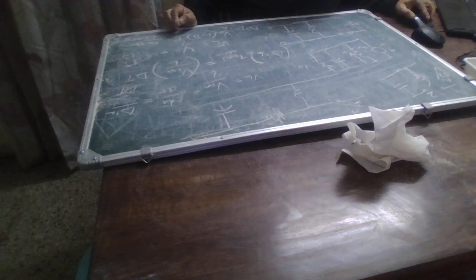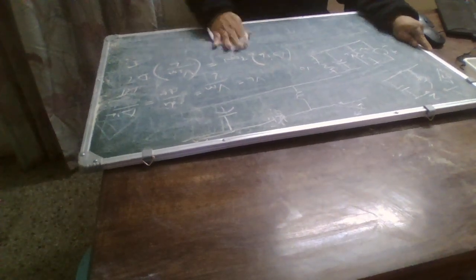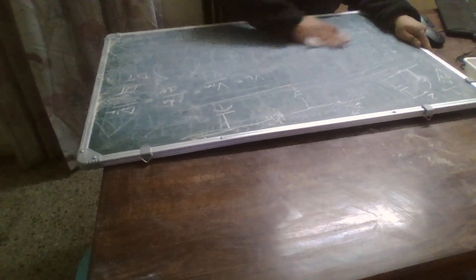Again, as we are taking a steady state operation, we will say that the delta I during the on time and the delta I during the off time, or the delta I closed and the open, the summation is going to be equal to 0. So we are going to equate it. It means delta IL on plus delta IL off equal to 0, and I am going to put the values that we have got. V input dT upon L plus V output (1 minus d) T upon L equal to 0.